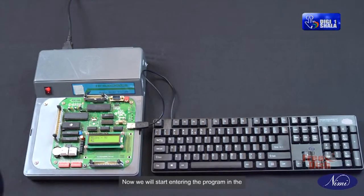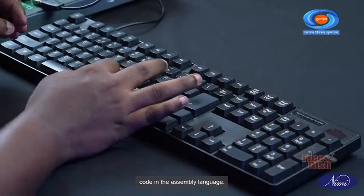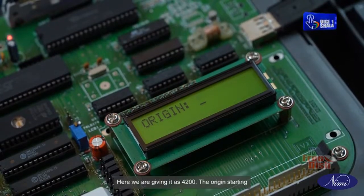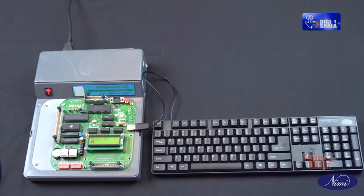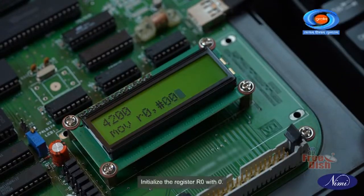Now we will start entering the program in the microcontroller kit. Click A on the keyboard as we are writing the code in assembly language. Click enter to proceed. Now give the origin for the microcontroller. Here, we are giving it as 4200. The origin starting address will change from kit to kit. Start entering the program. MOV R0, #00. Initialize the register R0 with 0.